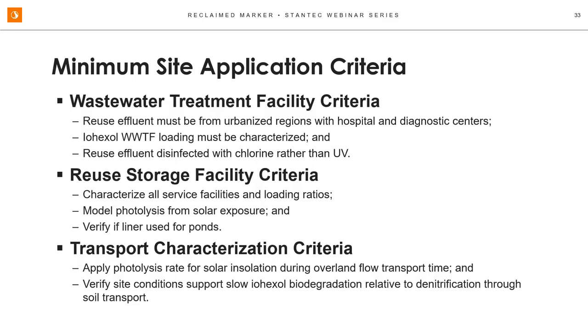You tend to not see much of this, say, Monday morning relative to Wednesday morning, because a lot of these facilities might not operate over the weekend. So you basically have to collect enough samples to get a statistical characterization, which is what you always have to do with wastewater effluent or influent when you're designing the plant. You have to understand the water quality variations.